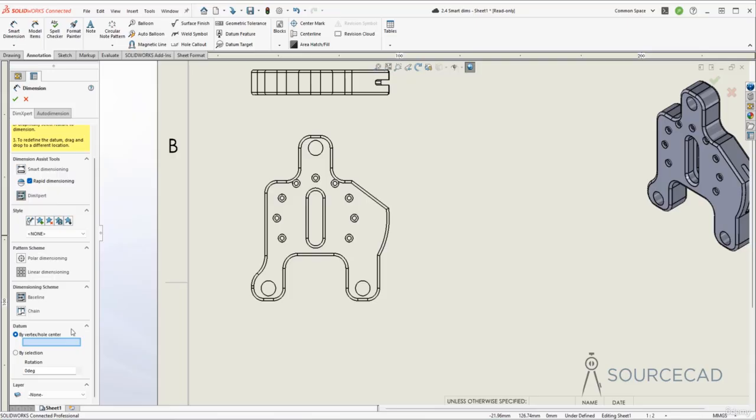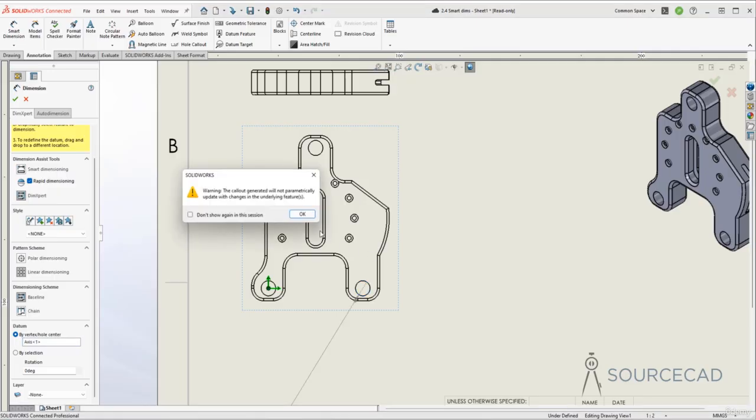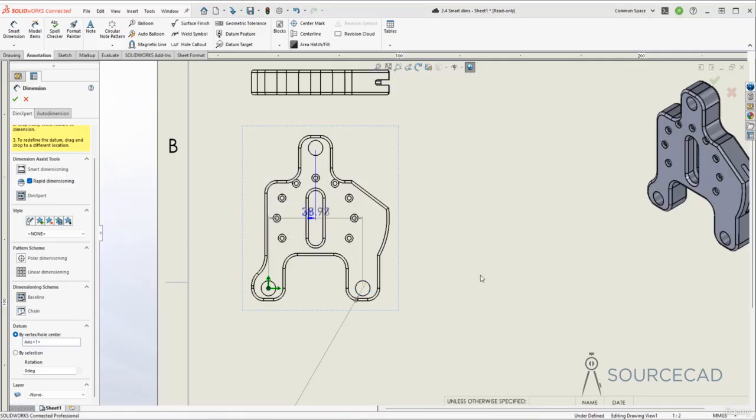So you need to select the base point or the datum from which all the dimensions will be measured. So in this case, let's just select the center of this hole as the datum. So I'll just click on this center right here, and the UCS will be placed right here. Now with this coordinate system placed on the datum, we are ready to select the feature. So now if I select a feature, for example, this hole, SolidWorks will add several dimensions. You just need to click OK here like that, and using all these dimensions, you can actually define the location of this hole as well as the hole dimensions.